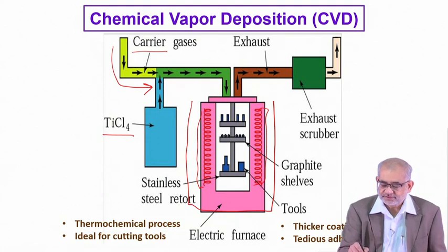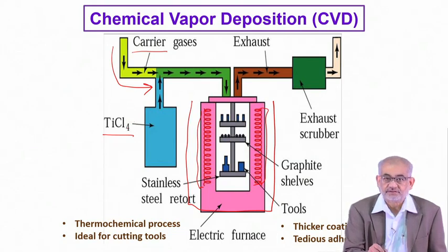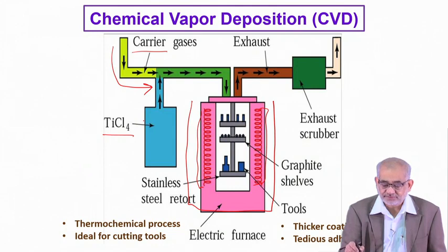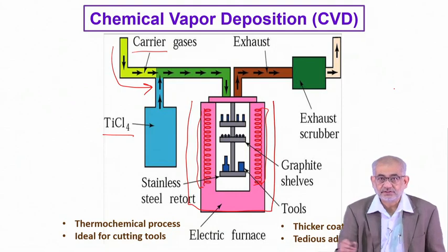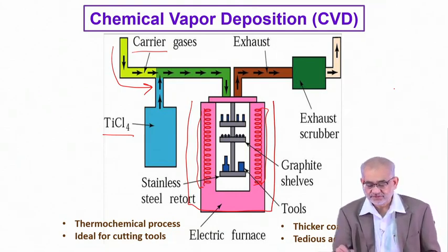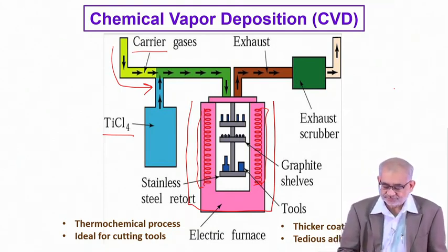They mix together, and then in the reaction chamber at the temperature, they dissociate. Hydrogen reacts with TiCl4 and produces hydrochloric acid vapor, and that vapor goes into this scrubber chamber, which is showered with water. The acid is then collected and taken out or given the requisite treatment before disposal.